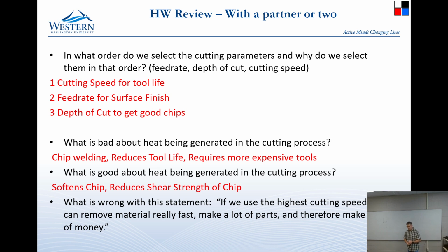Which, like the chip loading or reducing tools. Okay, yeah, so we can reduce the tool life, and if we reduce the tool life enough, then we spend all of our time changing tools or paying for new tools. So tools have gotten pretty expensive recently.